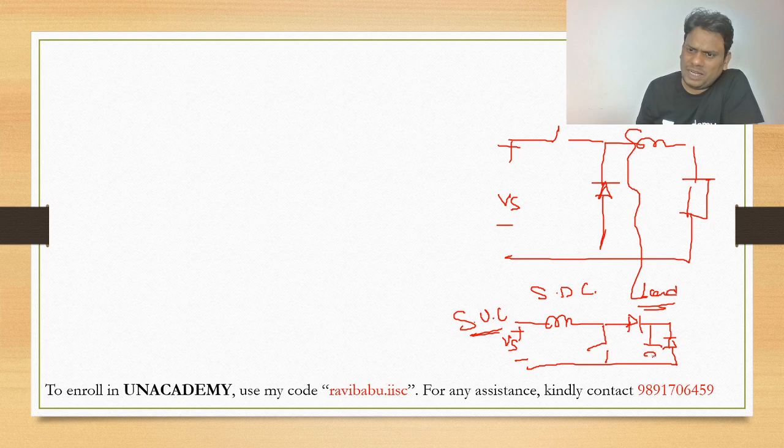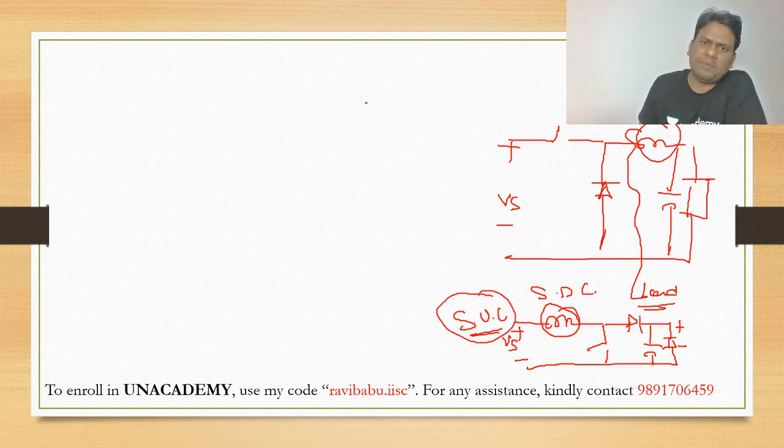Now sometimes, my dear friend, we can connect one capacitor across the load also to control the ripples of output voltage. So if the inductor is present on the load side, it will be step down. If the inductor is present in series with the supply, it will be step up.